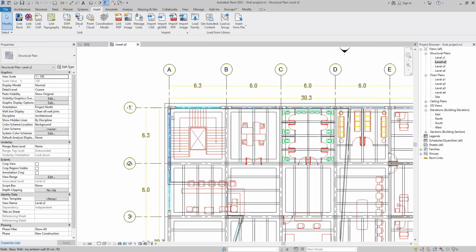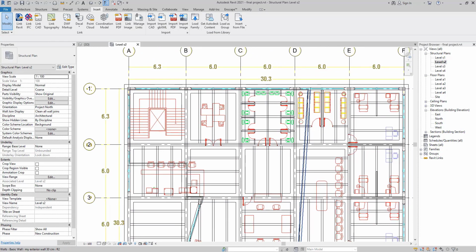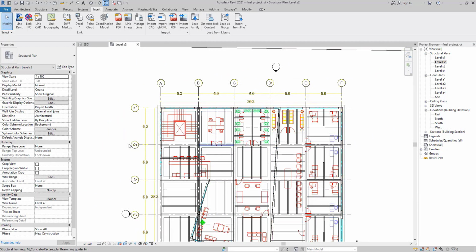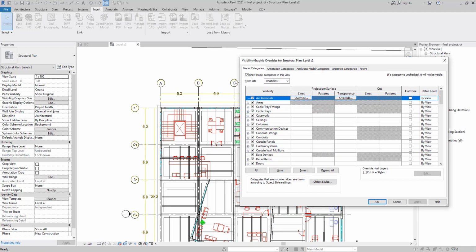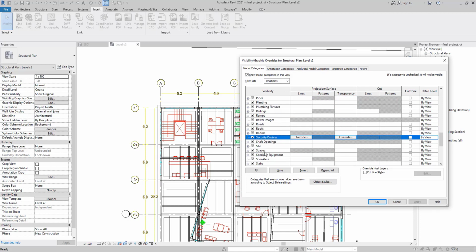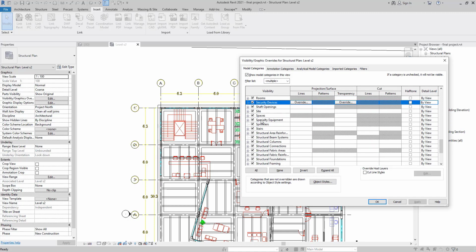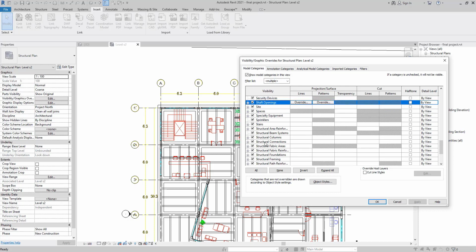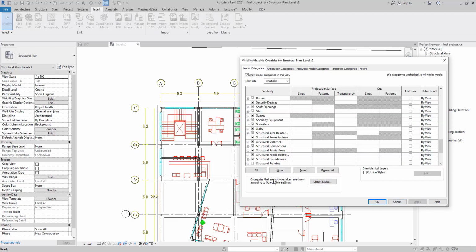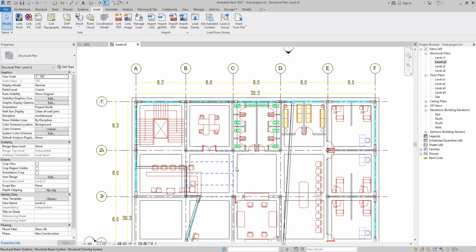And after that we are going to start drafting our wall here as well. So for having a better view and no problem, we need to hide our beam system by going to the visibility and graphic and model categories. We can find our structural beam system, which the name is, let's find it, structural foundation. No, structural framing. We are going to choose our structural framing, and after that apply. So we will see we can work right now without any problem. Then we are going to start working.